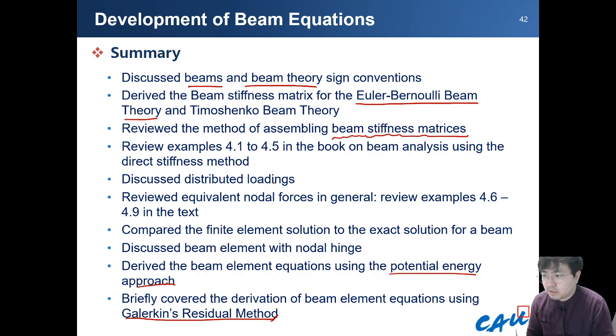However, the most important thing today is equivalent nodal forces. In 2D and 3D simulation, this equivalent nodal force is also used for changing the surface forces, I mean the pressure, to specific nodal forces. So please remember how to change a distributed pressure to specific nodal forces.